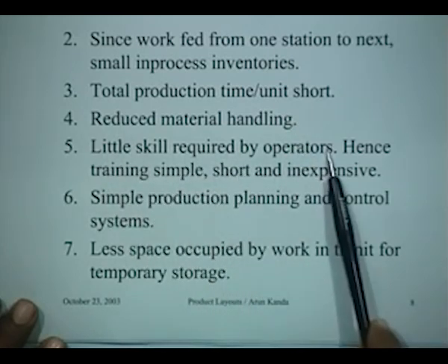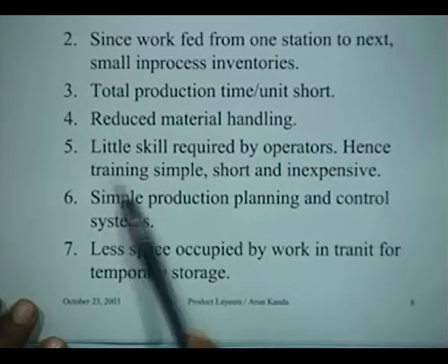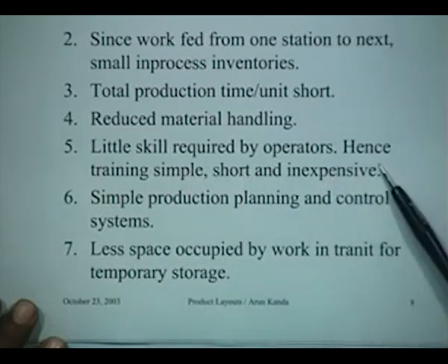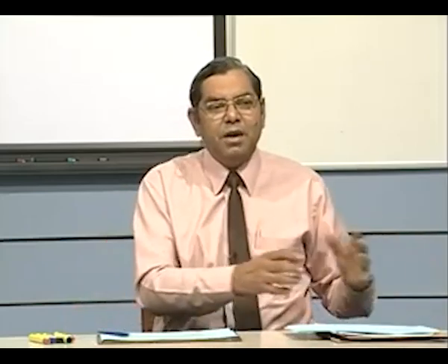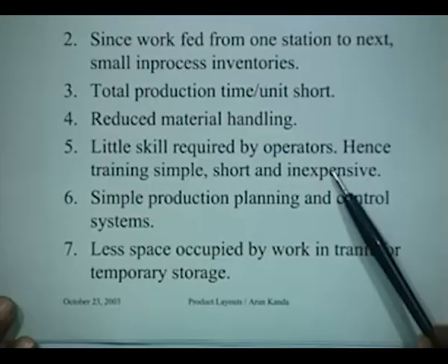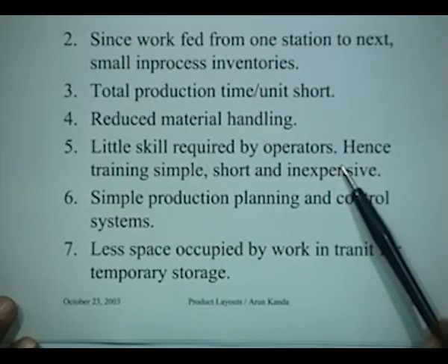Little skill is required by the operators. Hence training is simple, short and inexpensive. Why? Because the operator is doing very simple kinds of things, right? His job might be to pick up the piece from here, operate a foot pedal where it is held, and then take the compressed air and do some blowing, and then probably release it and send it to the next operation. So he has to do a couple of things which can probably be learnt in half a day. So training is quite simple and inexpensive, unlike the training for a process layout.